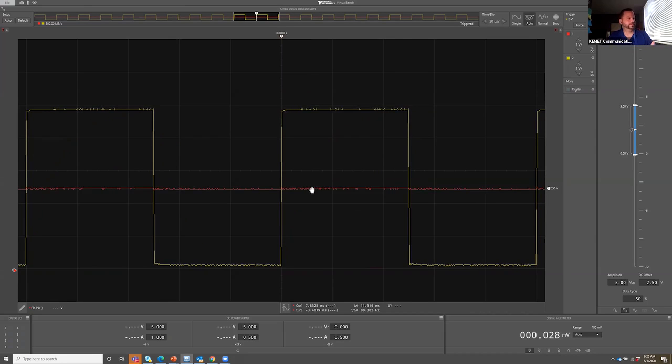And the voltage across the capacitor is, or at least you're not seeing anything on the output. What you're actually seeing is this 2.5 volt offset. That's because the only thing that this circuit here is passing is the DC portion of the signal. I have my function generator set up to go from 0 to 5 volts with a 2.5 volt offset. So a nice little square wave from 0 to 5. And it's just passing the DC offset.